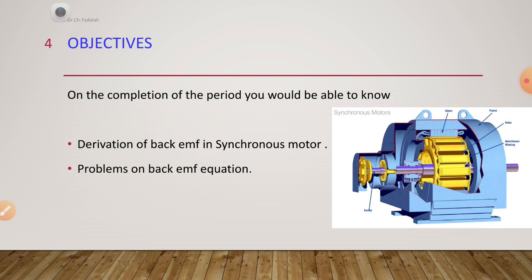During this period, due to the angle alpha between the stator axis and rotor axis, alpha decides how much armature current has to be drawn from the three-phase input supply at the phase angle power factor, to develop a small amount of torque to meet inherent losses like friction and windage losses, iron losses, that may be eddy current loss and hysteresis losses, and somewhat copper losses in the stator and rotor.